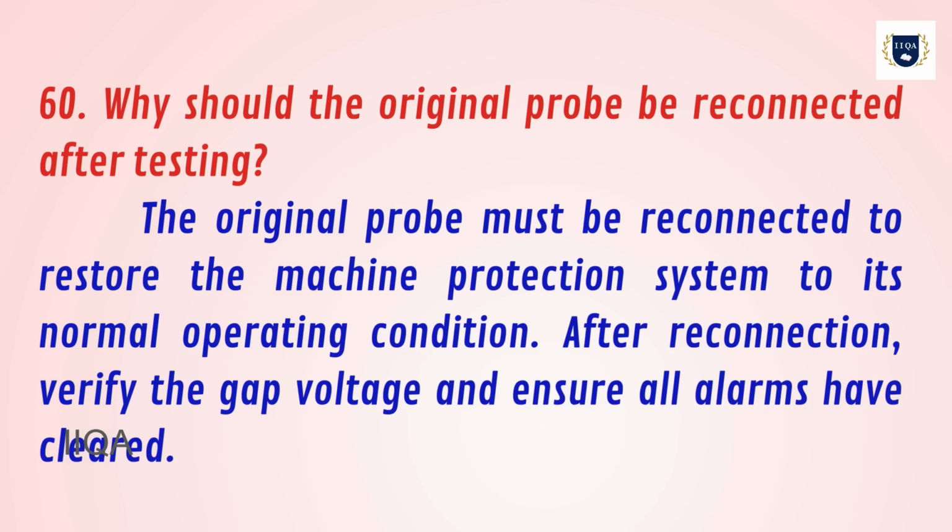60. Why should the original probe be reconnected after testing? The original probe must be reconnected to restore the machine protection system to its normal operating condition. After reconnection, verify the gap voltage and ensure all alarms have cleared.